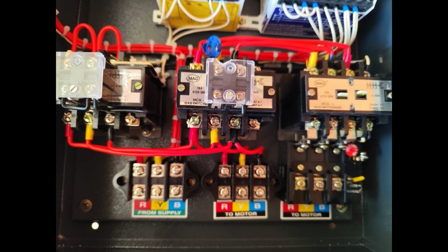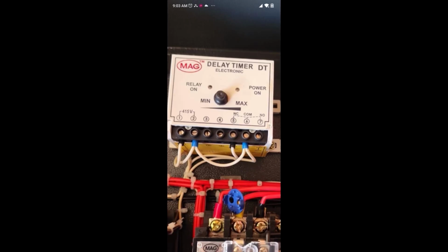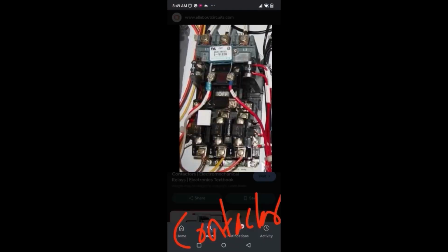The automatic control circuit includes a timer, an auto starter, 3 contactors, main star delta configurations, and power supply, that is the auto starter. The side portion is given in the circuit diagram. That is the auto starter connected to the delta 2 contactor, backside portions. Remove the link and give the 6th, 7th, 8th terminals to the stop and start button.